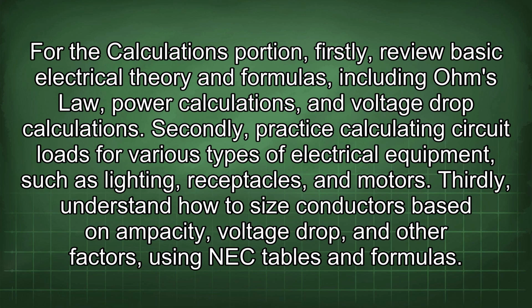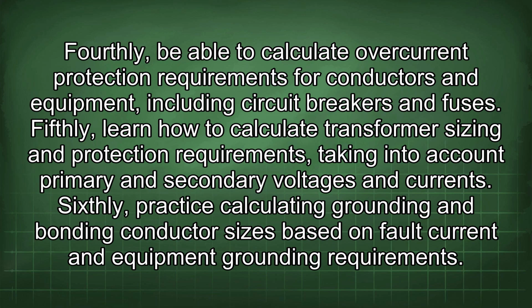Secondly, practice calculating circuit loads for various types of electrical equipment, such as lighting, receptacles, and motors. Thirdly, understand how to size conductors based on ampacity, voltage drop, and other factors, using NEC tables and formulas. Fourthly, be able to calculate overcurrent protection requirements for conductors and equipment, including circuit breakers and fuses.